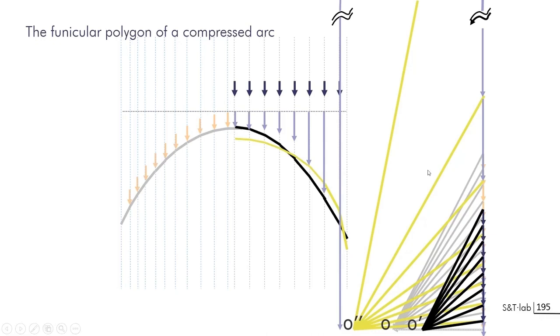And so it shows you that this figure is very hard to equate, and you have a force that is nearly infinite on the side. And in any case, you will need more forces on the side to equate such a system. So it explains why this is not widely used in cathedrals, for instance, in the last time, and that you will have devices such as flying buttresses on both sides to create the system.